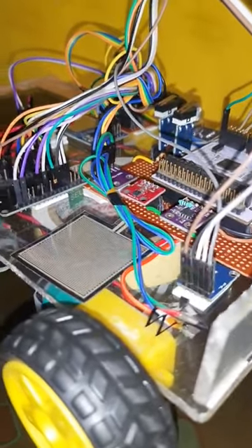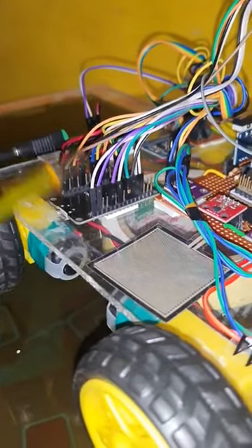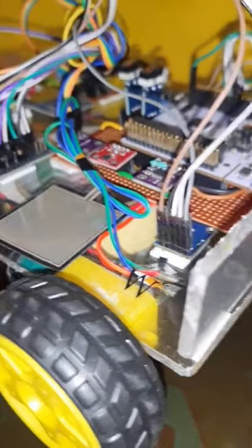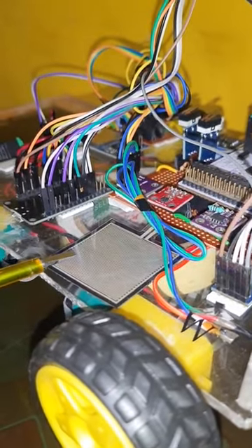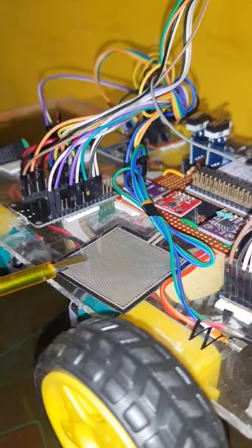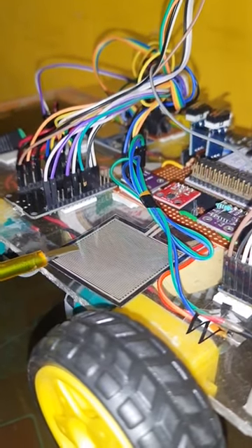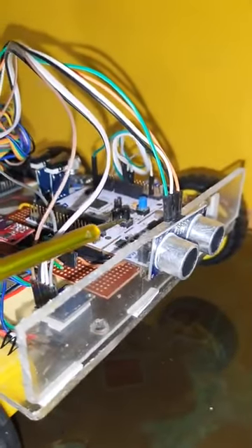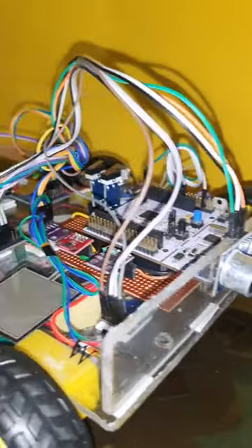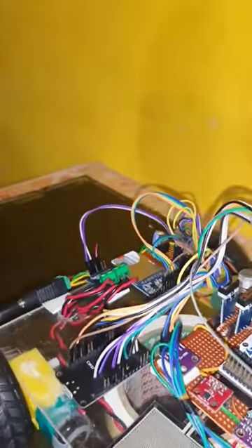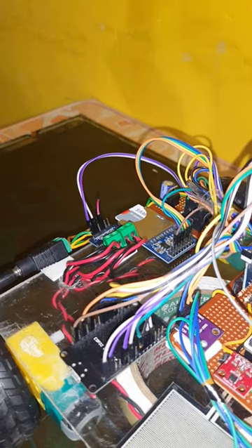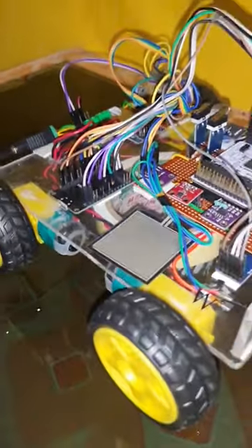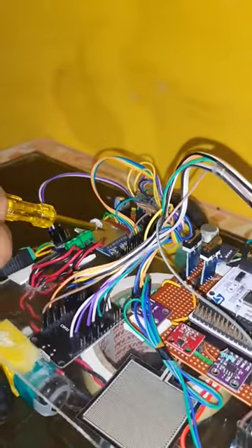On the ESP32, we are using a tilt sensor to ensure the position of our car, then a force sensor to find out the impact if a car accident happens, then an ultrasonic sensor for detecting the vehicle-to-vehicle distance, and finally the SD card module. The SD card module we are using as a black box, so all the data of these ESP sensors and STM sensors gets fed into this SD card module.